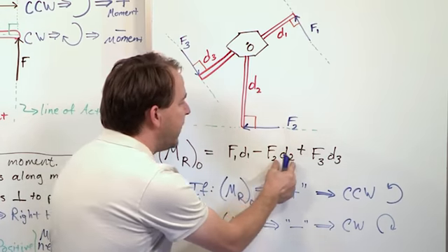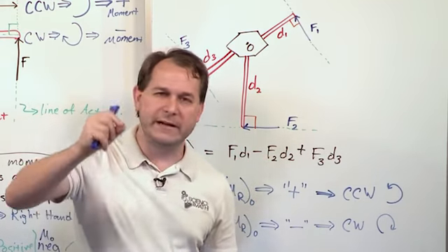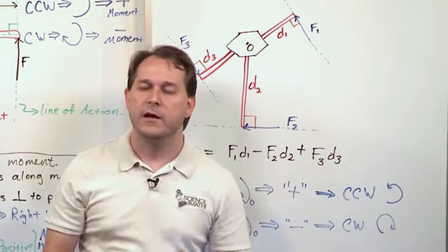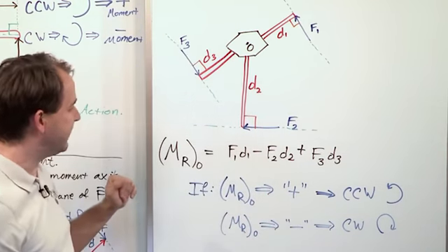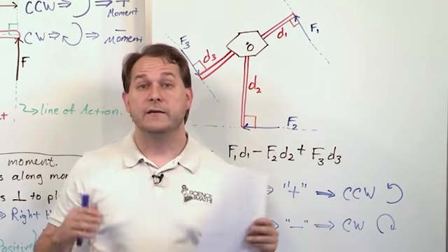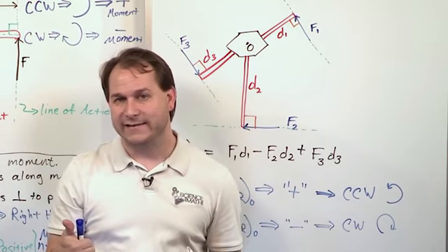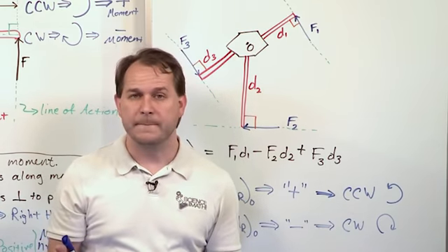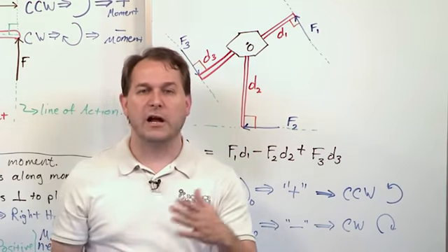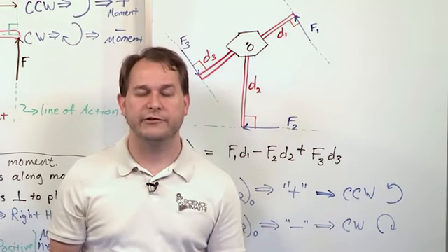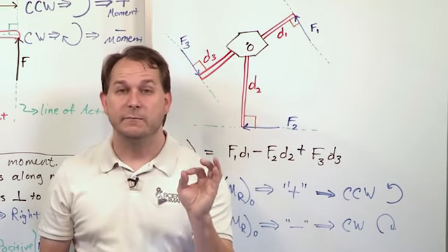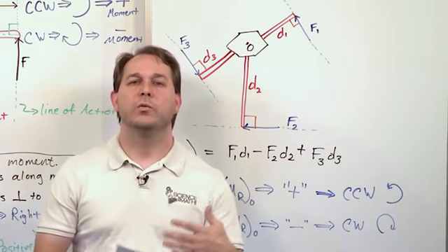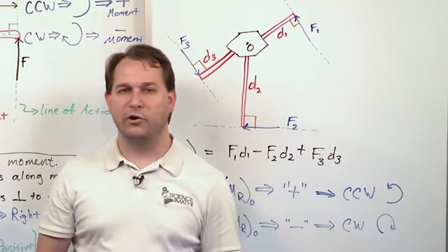The fact that these are multiplied is just the definition of the moment, and I'm warning you time and again that it's only the perpendicular component of the force along the line of action that actually does anything. We're going to get into more detail in the next section about why that's the case, but for now, just know that the moment of a force is always around an axis, that it's the perpendicular component of the force times the moment arm, which is the distance, and that we have a sign convention for counterclockwise and clockwise to bookkeep the directions of the rotations. And in the back of your mind, keep track that the moment is also a vector quantity. So when we get to 3 dimensions and we're looking at arbitrary rotations, we're going to end up representing them as vectors and eventually cross products.